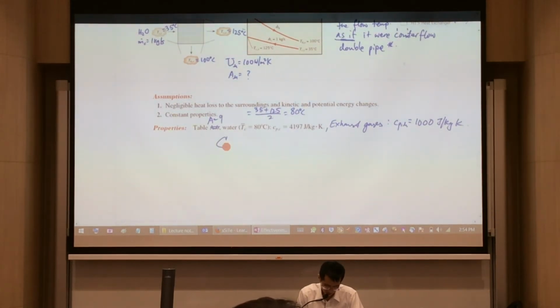C_c for the cold fluid is m dot c Cp,c, equal to 1 kilogram per second multiplied by 4197. If you use the Holman textbook, you get a slightly different specific heat value, but here I'm adopting the material given last week. So you get 4197 watts per Kelvin.